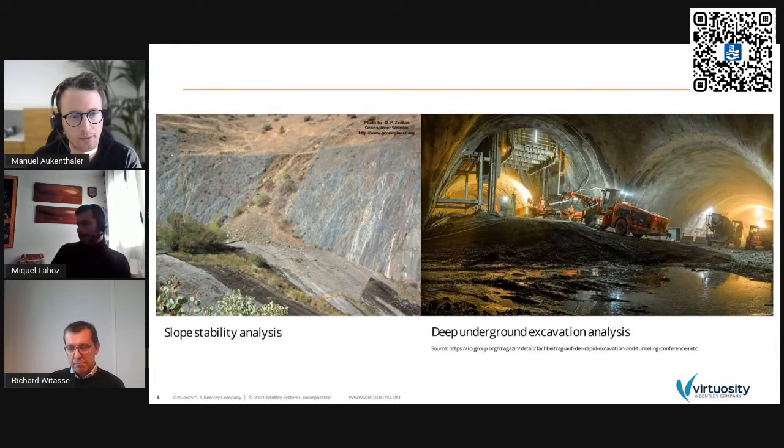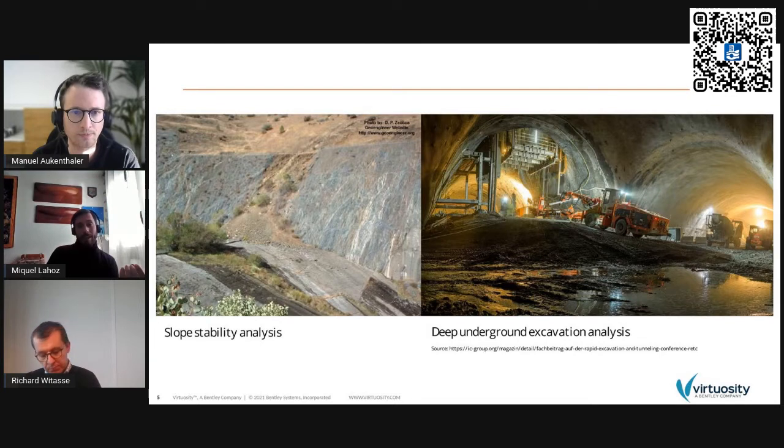Yeah, indeed. If you come like me from other engineering specialties, your first question is how do I characterize this rock material? But when you're in rock projects, you're not dealing with the rock material, that's just half the story. You're dealing with rock masses, and those have the contributions of both the rock and the many discontinuities that are there. And it's their mutual interaction that determines the behavior of the system. To give you an example of how this manifests into scale effects, if you take a sample of rock on the field, you bring it to the lab, and you take 3 specimens of different sizes of that same rock, the smaller one will be the one that has the stronger capacity. And as you move to larger samples, that capacity will decrease.